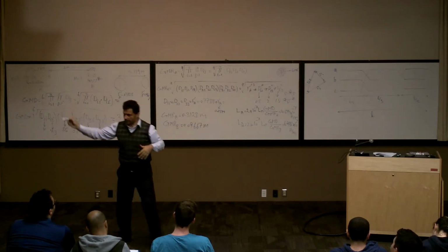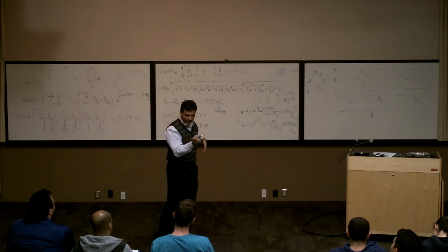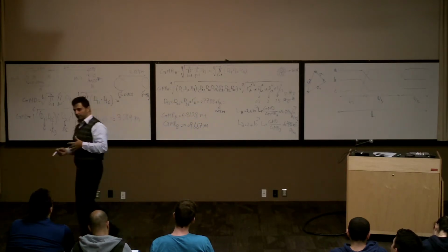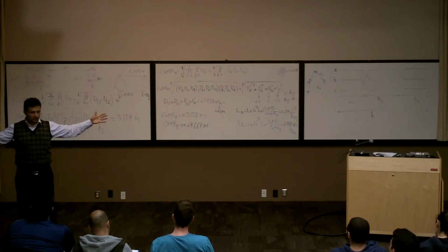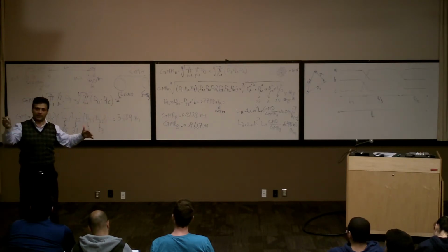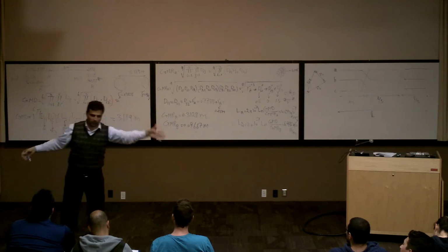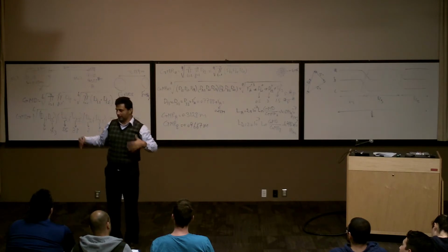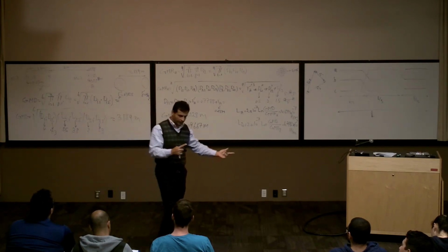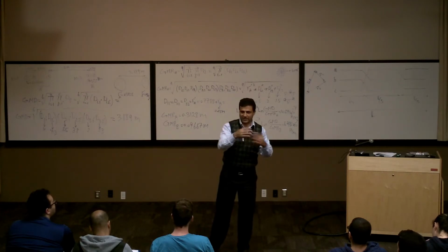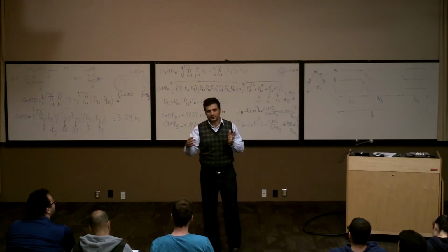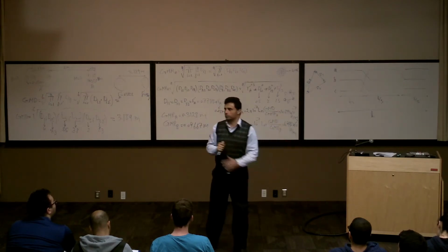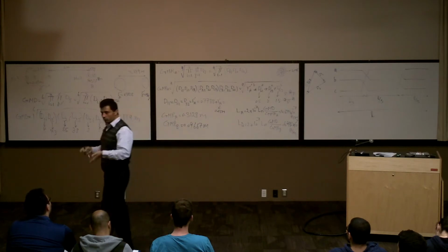But transposing is not that easy, because you think about this transmission line, phase A is coming here, now you have to change it, bring it here, and take it over there, right? So what they do is maybe every 5 towers, A is going to be on the right side all the way for 5 towers. B will be in the middle, C will be on the left side, for example. For the next 5 towers, they put A in the middle. They do this change as minimally as possible because this has a cost. To bring phase A from left to the middle, from the middle to the right, you have to pay money for that. But you have to make your system balanced.